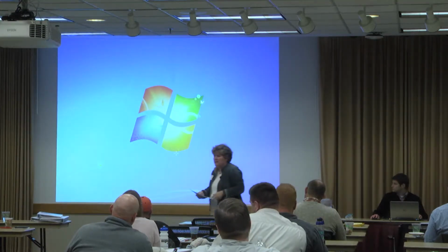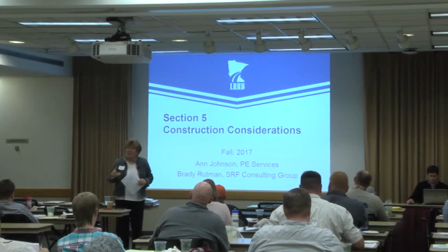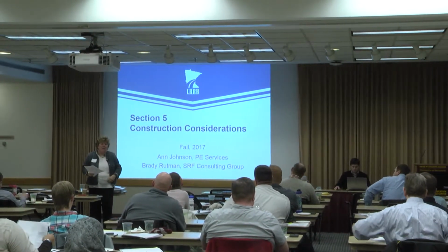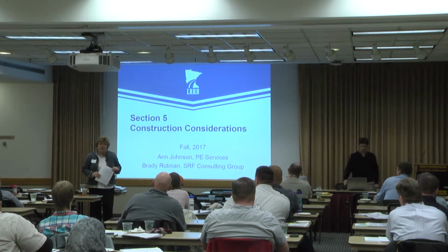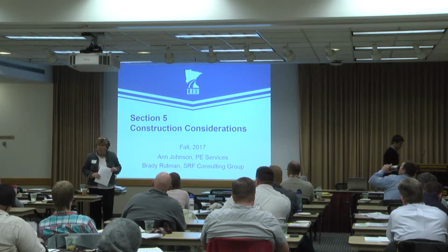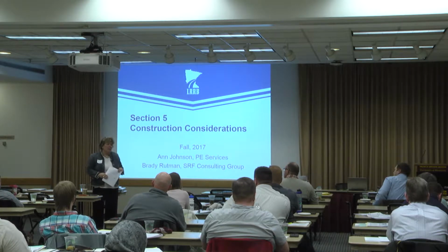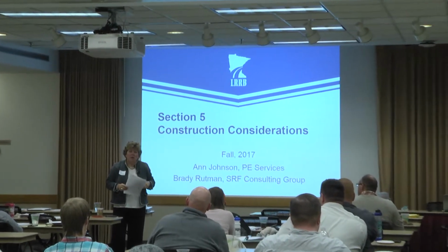I guess before I even get into the slides, I wanted to offer my 2 cents on best practices for construction. First off, we already talked from the standard plan. We're given the direction to cast the landing separately. A lot of times we are designing in the field and just trying to make grades work. Sometimes, even if we are given elevations or spline grades in the gutters, they don't work. So figuring out where the landing needs to be and making sure it's placed separately will help with a lot of potential problems. Watch the gutter grades and slopes.